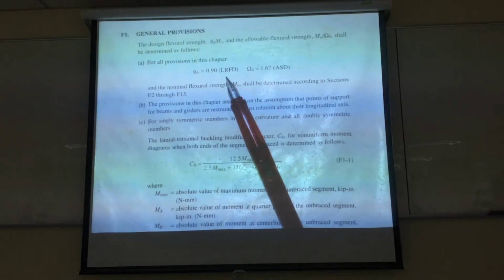You have to consider it a little bit before you just take the number to use, and the unit will be pounds per square foot. It will be a different unit, so you need to convert it into, say, Newtons or kilograms per square meter. And then in ASCE 7, it does not include just the live load. Well, you will have the dead load.